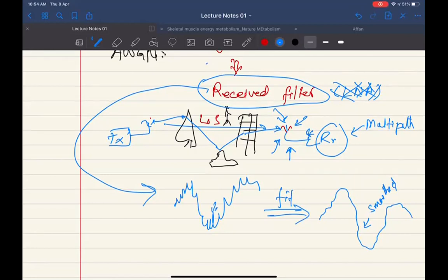And the filter has to be carefully chosen because sometimes you have this fluctuation important and you filter it out and you get a smoothed version for that one, which means that you are losing your information. This little bit of fluctuation was not noise, but the filter considered it as noise. So here it was wrong filtering.